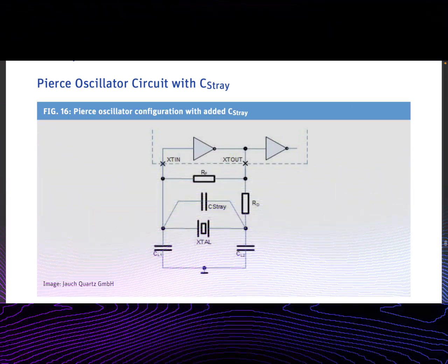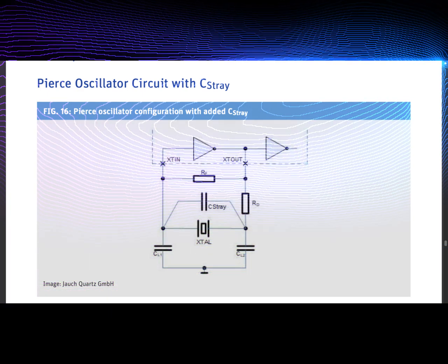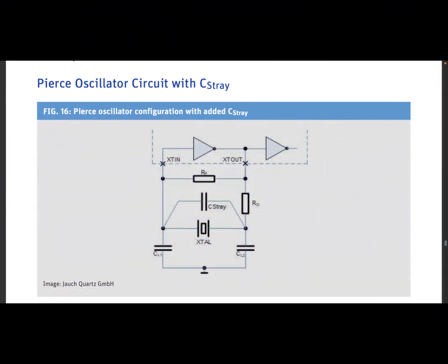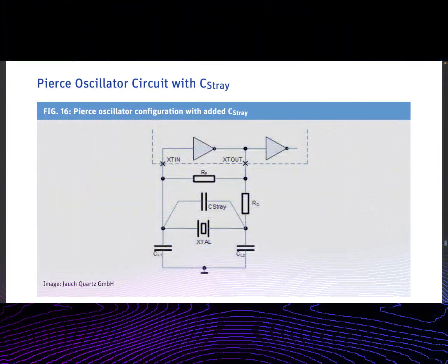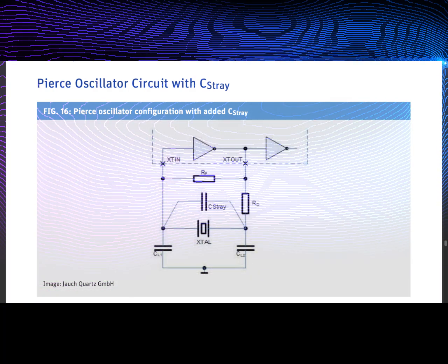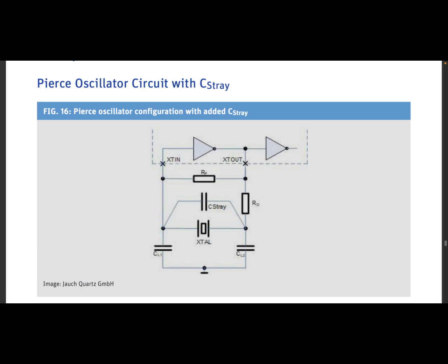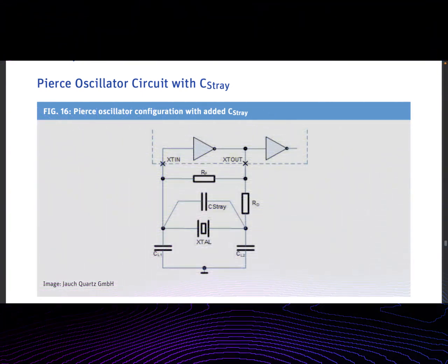For each of these vibration modes, an optimal cutting angle is used, which controls the frequency characteristics of the quartz crystal resonator over the temperature range.